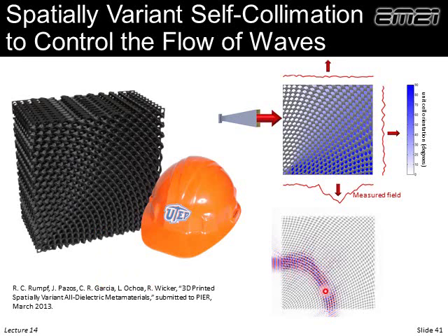And so here's our first simulation. It's kind of ugly, but I'm attached to it because it's our first simulation. We have much prettier things now. And here is a look at the lattice. The blue background is showing the tilt of the lattice, and we go through 90 degrees of tilt. We illuminate it with a horn, and these red lines are our measured data. There's about a 20 dB swing here, so we have about a 100-to-1 ratio. But we can see the beam coming out.